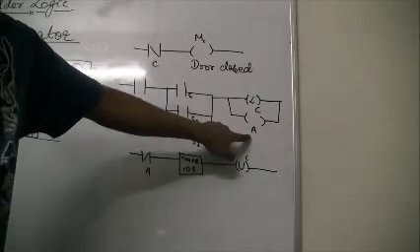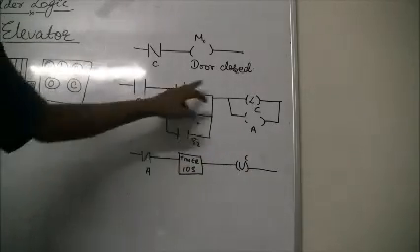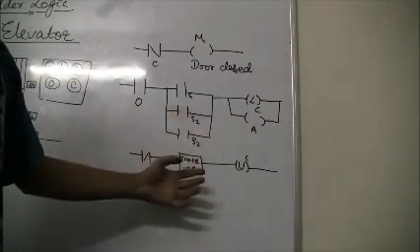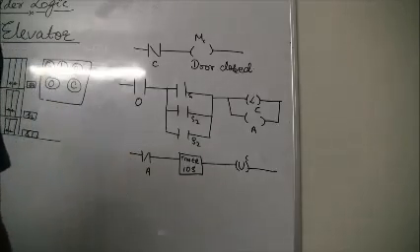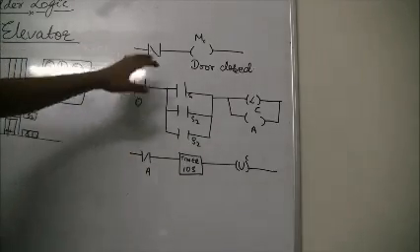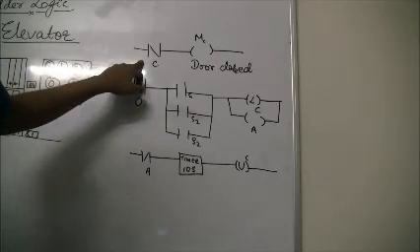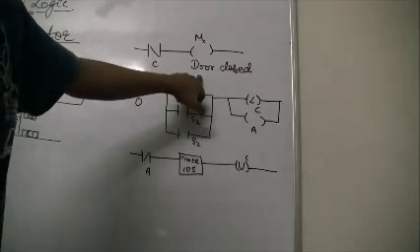And here it's a dummy output. Why? This output is simply the name of the switch. So when you go here, it toggles the switch. Once the timer starts, automatically after 10 seconds this goes and it unlatches C, and once it unlatches C, it comes back to its closed position, and once it comes back to its closed position, the door closes, right?